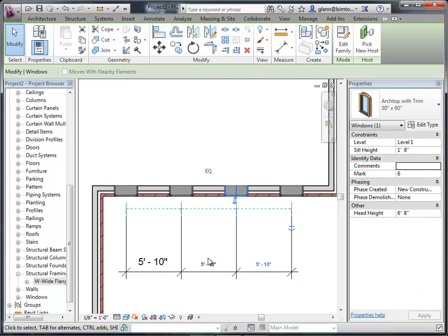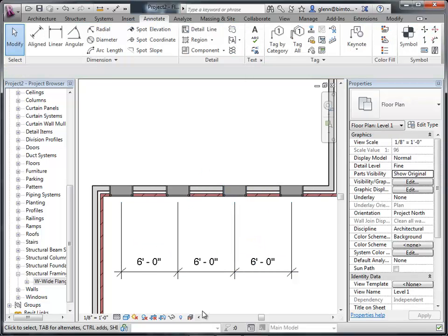In fact, even in here, I should be able to say, let's do 6, 3 evenly spaced at 6 and kind of get it that way. Whatever it is, it sort of makes the most sense. But the equality constraints are very handy things for doing things like placing windows, the things that are a very regular rhythm. You get a whole bunch of columns that want to be regular rhythm. You have furniture to be placing that are regular rhythm. Like that over there.